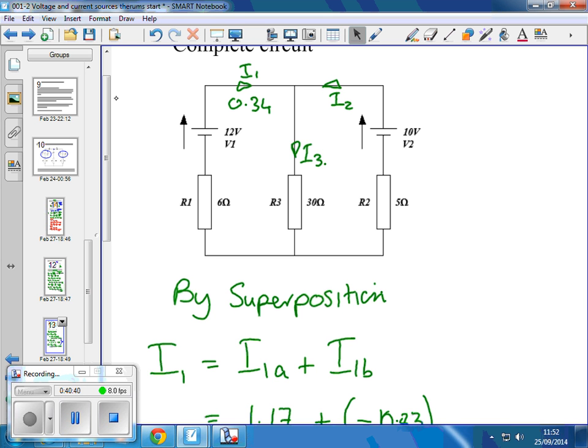We've got to get this concept now of we're analysing this circuit at an instant in time. If we change anything about it slightly, we change that load, everything's going to change, be a different instant in time. Or if it's an AC circuit, the voltages are changing most of the time. If there's any reactive components in the circuit, you could have a transient condition where things are changing. And therefore, the direction of that current could change.